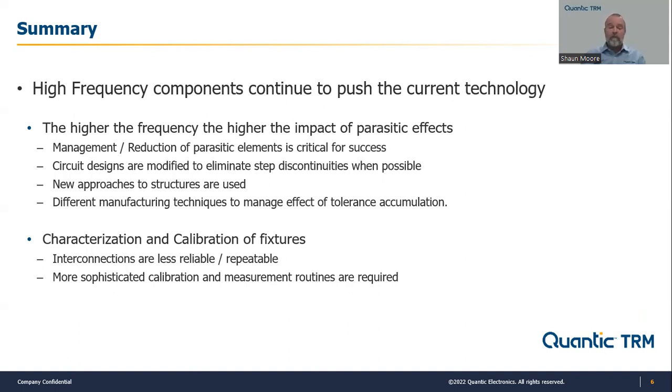overall circuit design. Also, going through there and making sure that we have some very good control over the propagation modes, making sure that the stack up is manageable, to make sure that we don't generate higher order modes as we're going through the construction, whether it be via spacing or the size or the thickness of the substrate that we're putting the circuit on.